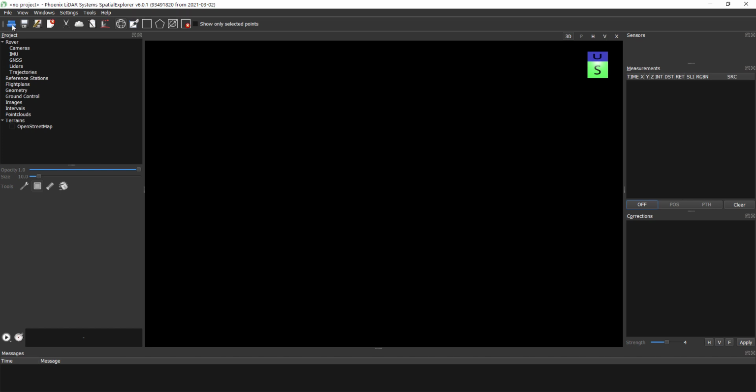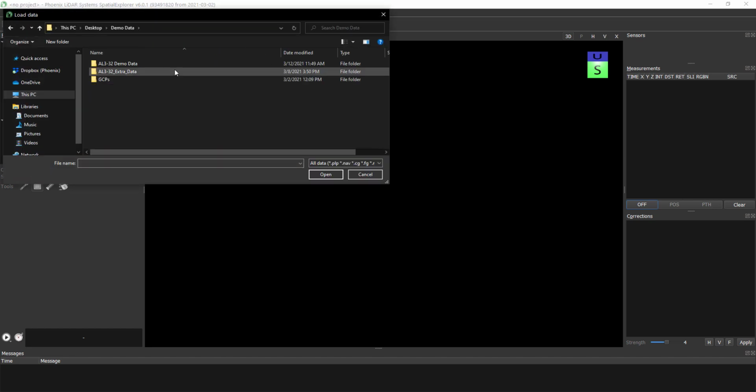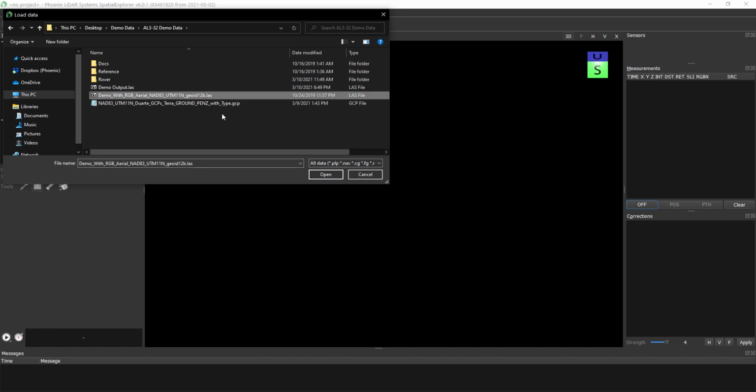And we're going to be using the Open File button and navigating to an outside LAS file. This is from the same system but created with a different software. And we want it to end up in NAD83 UTM 11 North, and it happens to be orthometric height utilizing geoid 12B. So let's go ahead and investigate our CRS wizard, and you can see how easy it is to import a LAS file.